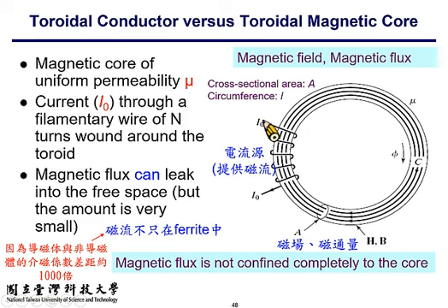So this helical-like electrical current winds around the magnetic core. This is made of the so-called ferromagnetic material, a magnetically conductive material, which shall produce magnetic field as well as magnetic flux within this ferromagnetic core.